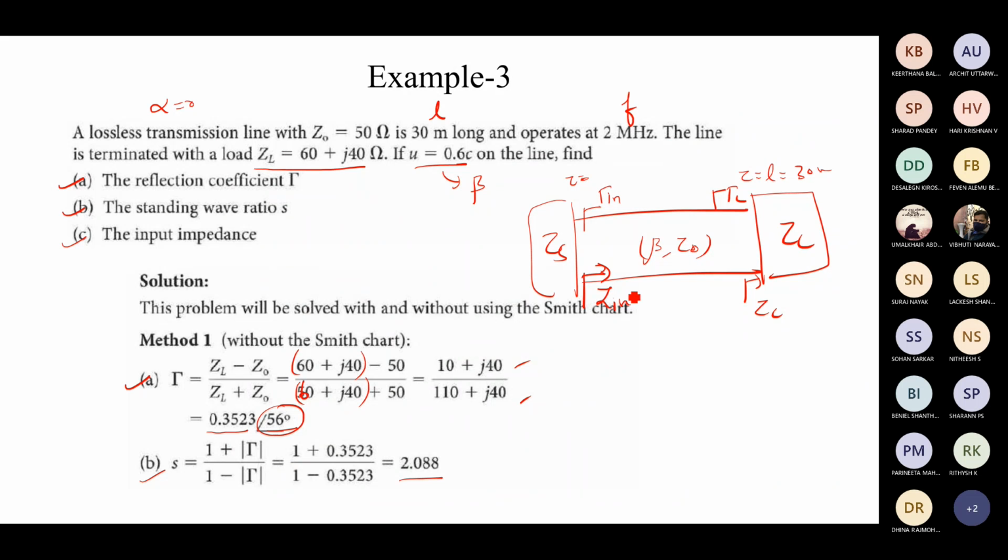Then we have to make some decisions on how to make this impedance the same, so that maximum power will be transmitted. In the future classes, we are going to see how to solve this problem. For instance, you can notice here that this load impedance is not at all equal to Z0. Not even the real value. The real value is 660 here, and here it is 50. Definitely they can't be matched. But there are some interesting concepts when you put the transmission line in a different way, so you can match it. That is what we are going to see in the future class.